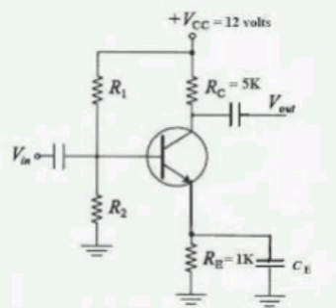Case when pressure coil is highly resistive, no inductance present, developed torque. The phasor diagram has IP at angle phi with V, and IC equal to I. TD equal to I1 I2 cos alpha dM by d theta, that equal to IC IP cos phi dM by d theta, TD equal to I into V by RP cos phi dM by d theta. TD is directly proportional to VI cos phi, so true power PT equal to VI cos phi.